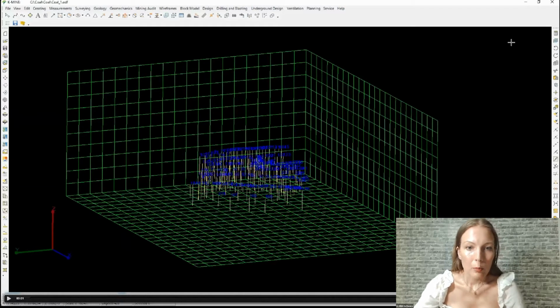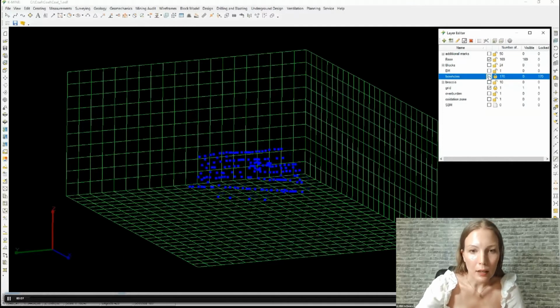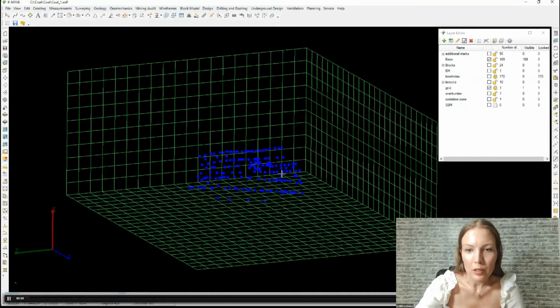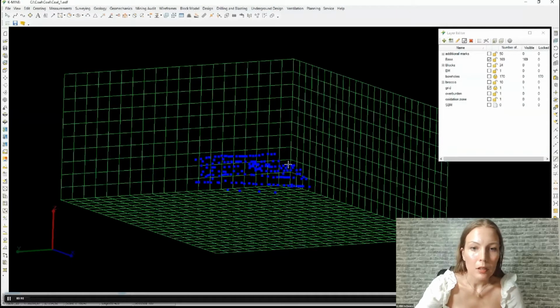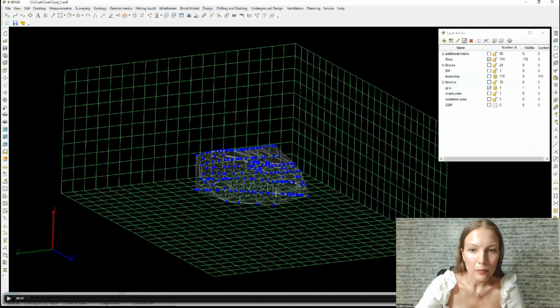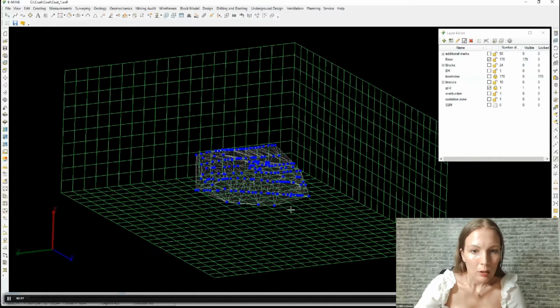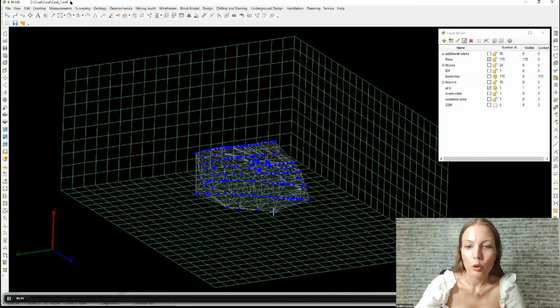Well, then in the processing type column, we're selecting the current value, and in the destination column, we're selecting depth. We push OK, and you can see that object marks were created from the database, and they contain Z marks values of the seam, roof, or floor, or bottom. So then we just open the layer editor and select point objects to create a seam floor wireframe.